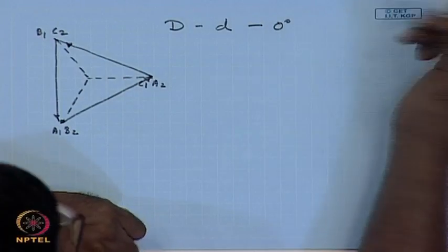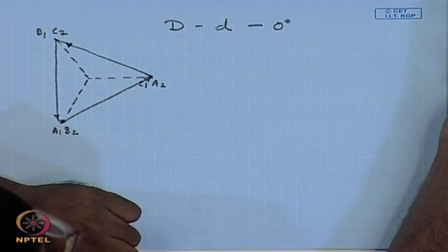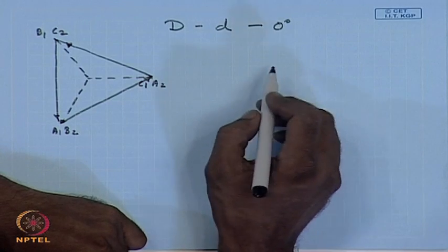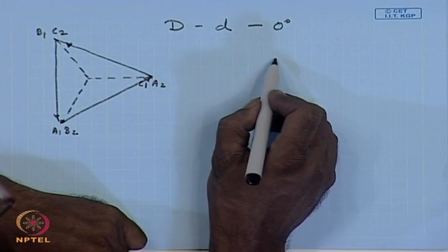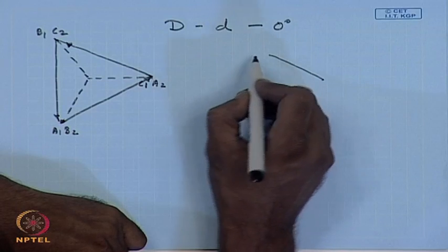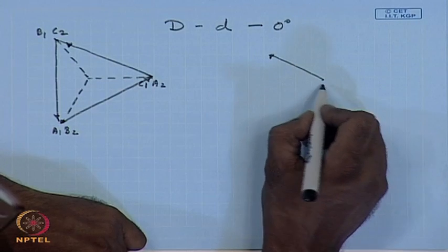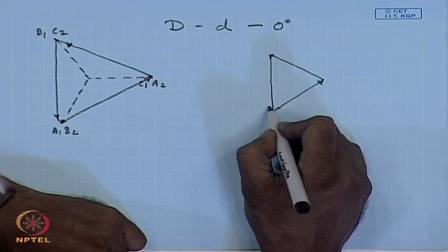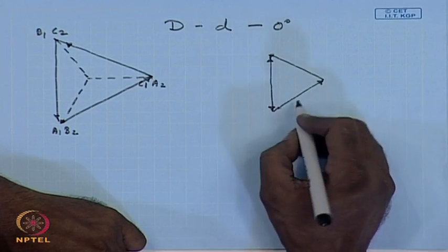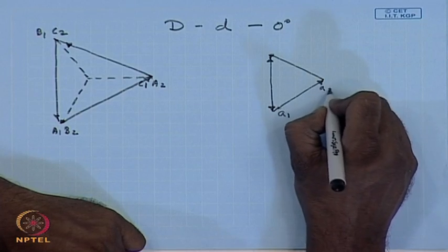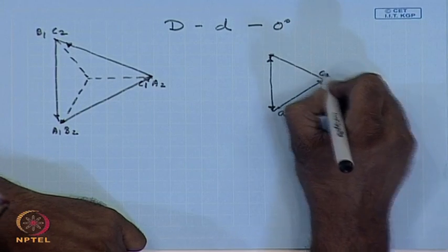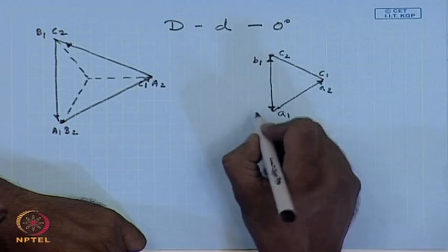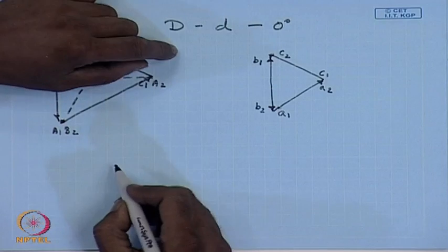DD 0 means line to neutral phasors are co-phasor. So, will be the line to line phasors. So, on the secondary side this will be the phasor, this will be another phasor and this will be another phasor. This will be A1 A2, this will be C1 C2, this will be B1 B2. Connection wise, it is simple.